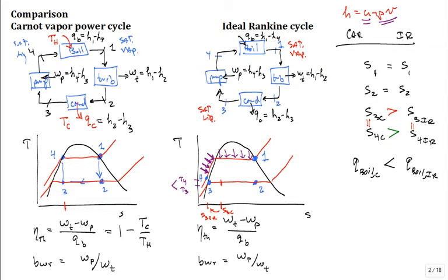Then from 295 saturated liquid to 295 saturated vapor, a lot more heat comes in this area. But that's the heating that occurred with the Carnot. So that last half is the same. So the ideal Rankine, there's more heat per unit mass going through the boiler. Okay. I knew that would be harder, but let's continue on.